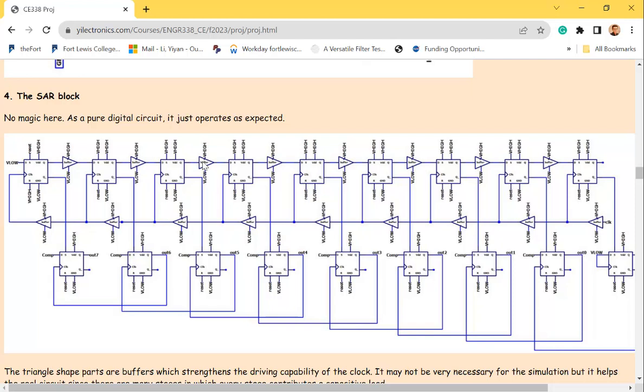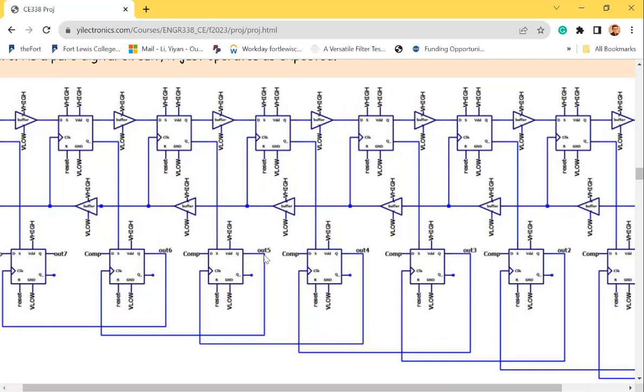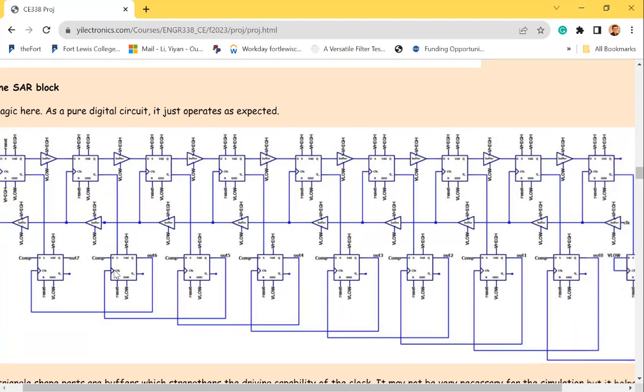Remember from the top, it's shifting the 1 to the right. So it's setting each bit in a certain sequence in order to provide a rising edge to the clock for the previous stage, right? But because it's zero active, it's basically all ones, and only one 0 appears at one D flip-flop in order to set it. It's zero active, it's setting it, right? Setting it is providing a 1. The 1 will provide a rising edge for the clock. Okay, does that make sense? No?